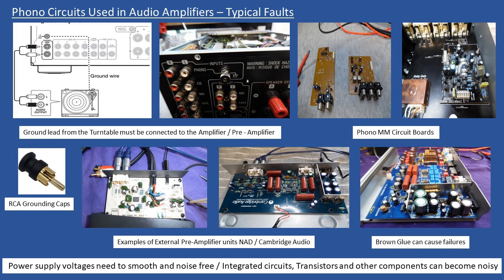Now if it's thermally sensitive, you have something called component freezer spray, and any workshop will have this available, and I've seen many amplifiers and pre-amplifiers where components go thermally sensitive. So the way in which you do that is the amplifier is working, and then after maybe a few minutes you start to hear this crackling or noise starts to come through, and you're looking around, you can't see anything, and then you use the freezer spray, and don't just take the spray straw off it and spray it across the board.